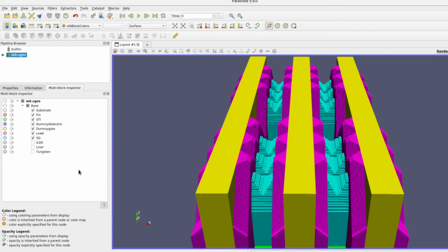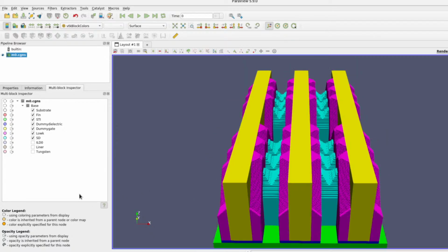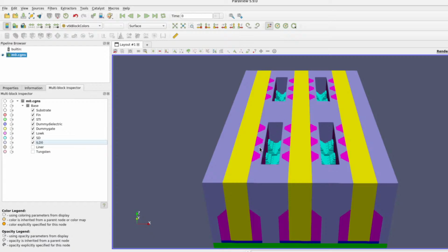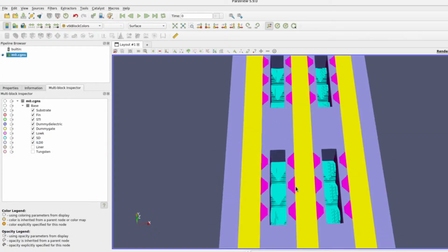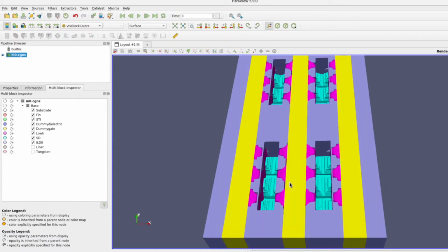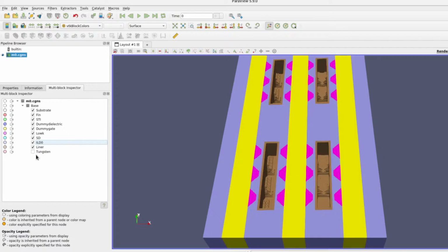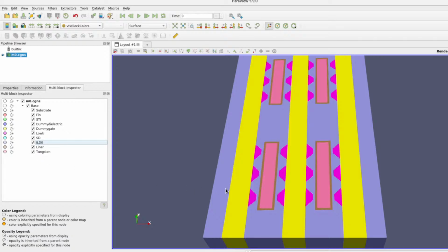However, I will just keep this same shape and the common terminology source drain for my own purpose. After that, now we add ILD 0. That is just deposited at first. Of course, at the initial time, there is no such hole, but that is patterned. So now, as you can see, source and drain parts are patterned. After that, we add liner metal, liner material, and tungsten is filled.